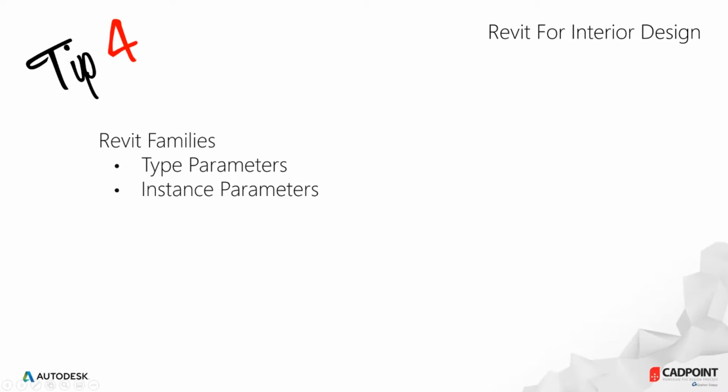So if I make a change to a type, it will change everywhere that type is used. If I make a change to an instance, it changes just that single element I have selected. And like I said, this always confuses people. So let's give this a little look here.